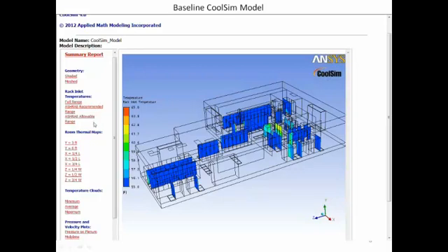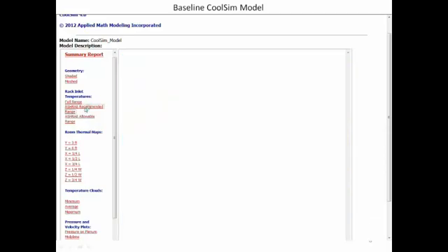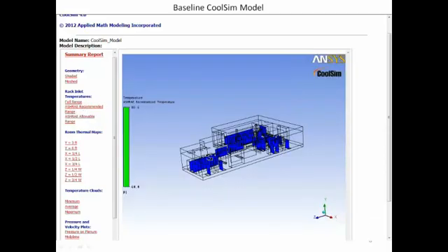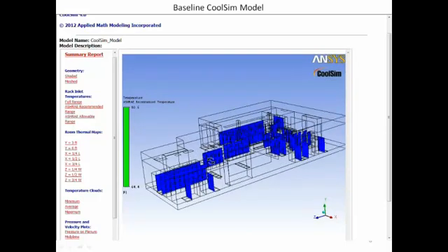So we added a couple more. This is something that we talked about with Magnus, and Liz did this implementation. We have two here. One of them is called the ASHRAE recommended range. This is really a kind of a go, no-go gauge. This one is, do my racks fit within the specification recommended by the ASHRAE standard for Class I rack inlets? The range, as you can see, is 64.4 to 80.6. Anything below 64 is going to show solid blue. Anything above it is going to show red.